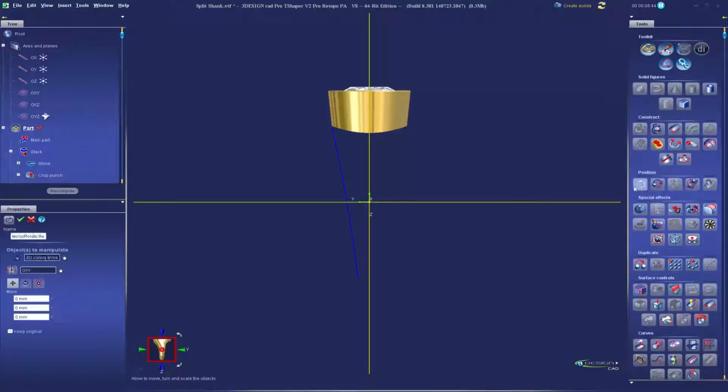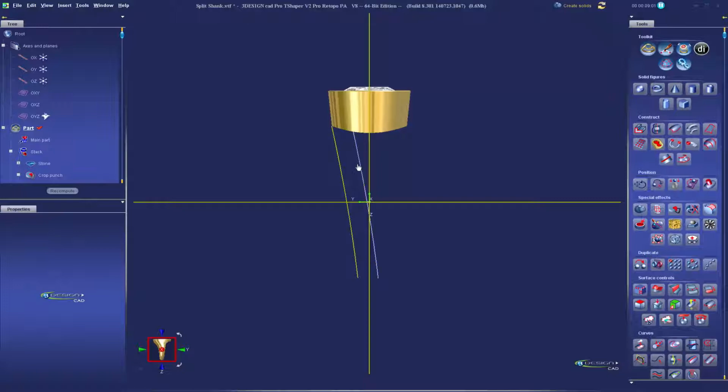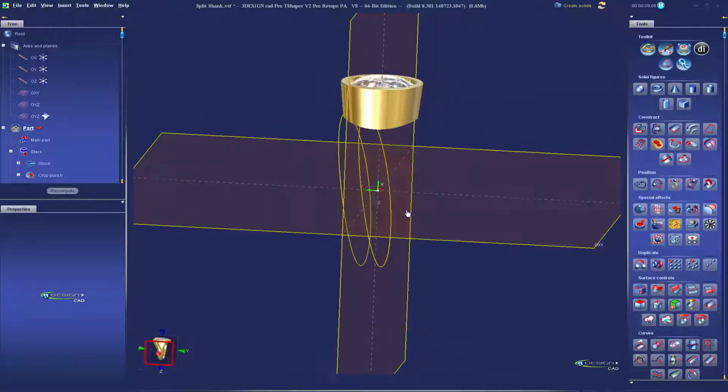By using move, rotate, and scale in the position section, I'm going to move it over how far we want the width of our band to be. I'm going to say -2 millimeters here. And I want to keep original. That'll copy the original. We have both curves, and now we have a very simple two-path setup. We know exactly how thick it's going to be, and it's all parametric still.